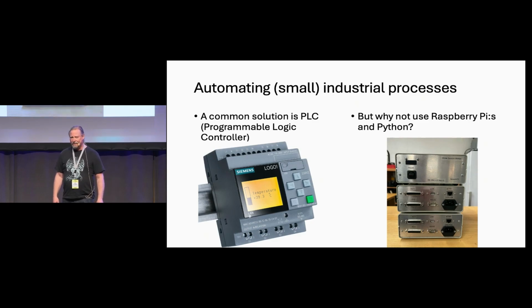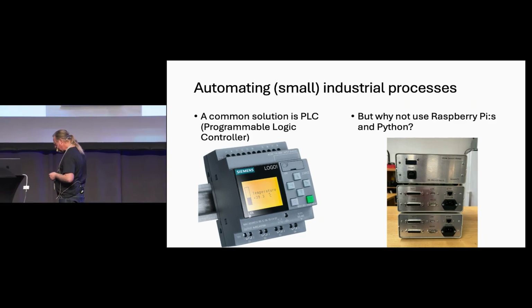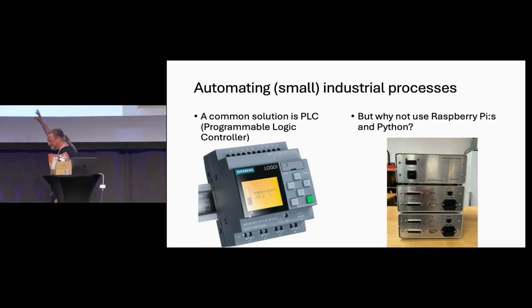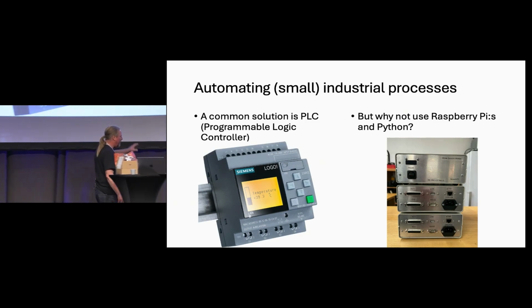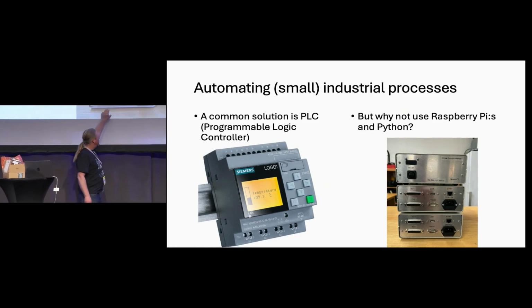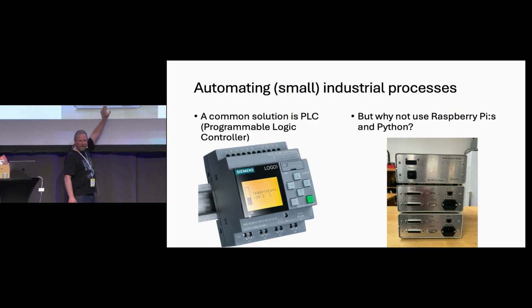And I was thinking, okay, that you would normally use a PLC for that, programmable logic controller. It's not very complicated to use those, but we already had a tech stack with boxes like this. In each of those boxes, there is a Raspberry Pi, there is a power supply, there is a DAC card. I will explain DAC card soon. And we use more or less the same box for every function. It's just different software and different configuration.